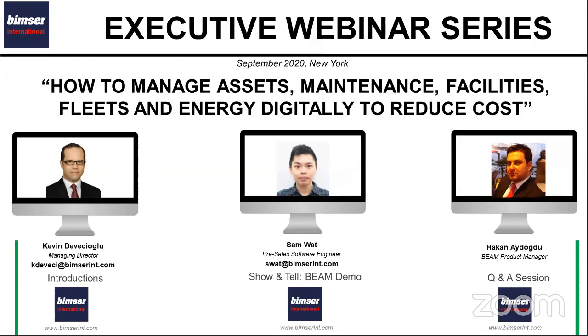They implement a predictive maintenance management program, which is very important because that may require smart sensors or PLC devices. With the help of this type of equipment, you can be predictive. Just like we mentioned earlier, with smart sensors or PLC equipment, you get certain symptoms from your machinery and equipment, typically temperature, vibration, and others.